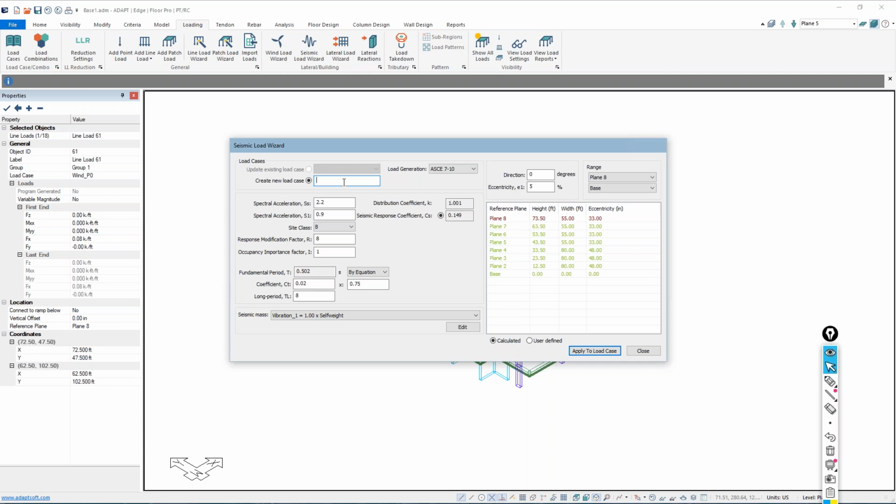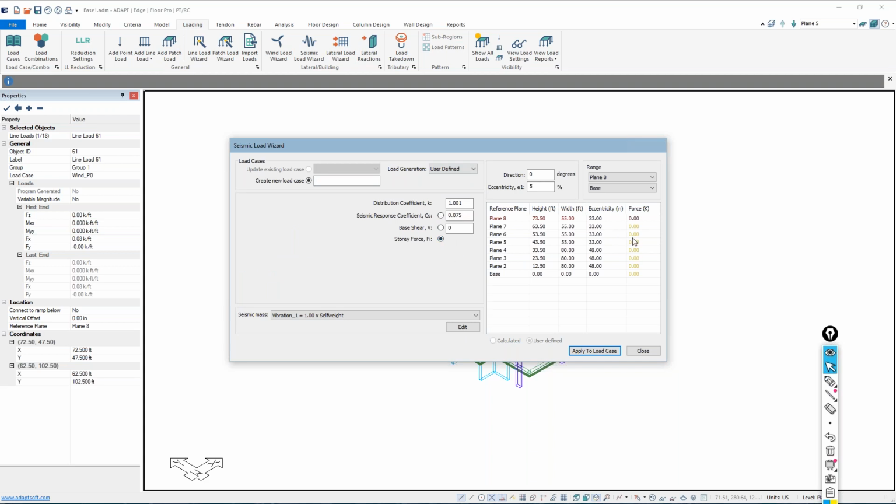So we can't assign the nodal loads until we actually enumerate the different nodes in the structure. That's why this really is just input into the solver. Once you actually enter the solver, then the program calculates the forces. If you want to see what the forces are, or you want to maybe have more control over the force entry, there's a couple of ways to do that. You could go here and say user defined, and you could actually just enter the story force here.